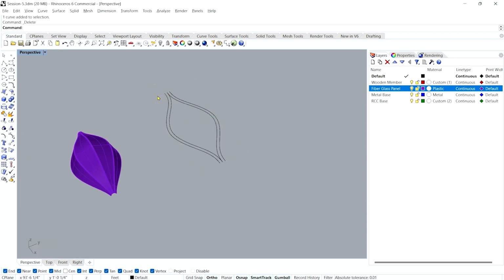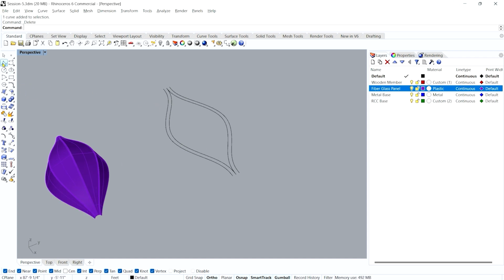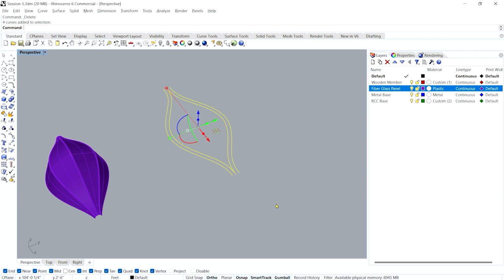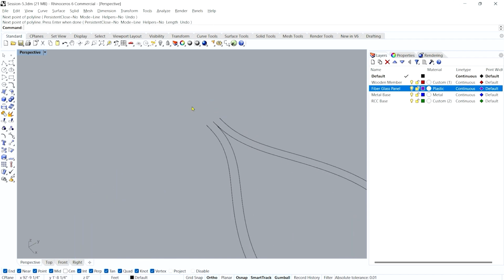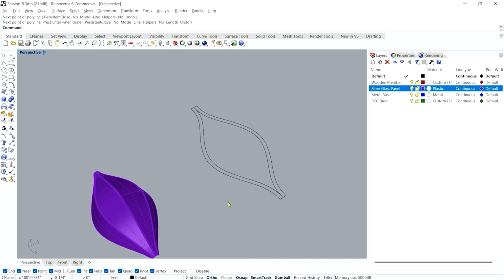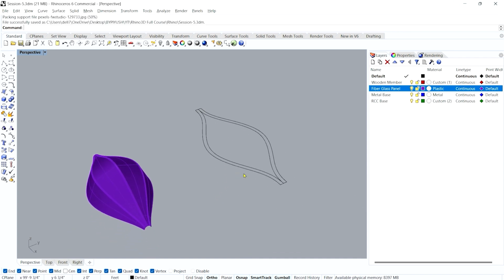Okay, let's delete. We will see that we have the grid already there. You can make a line or select and type close curve. It will automatically close this also. So what I will do, I will make them manually. I will select the polyline and close these one by one, not all together, right? So it will be easy for me to extrude. Close this. Now what we are going to do, we are going to extrude this to 1 feet 3 inch,